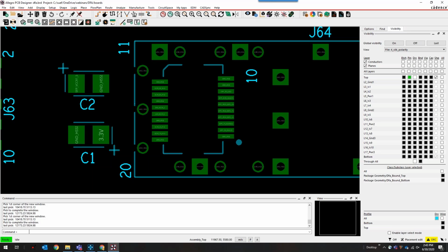So our first question is, can DFA single logged errors be approved or somehow marked to be ignored? Yeah, you can waive the DFA errors if you get them in the board, and you can accept them by just waiving them in the board file, and it turns the DRC marker 90 degrees so that you know that you've looked at it and addressed the issue.